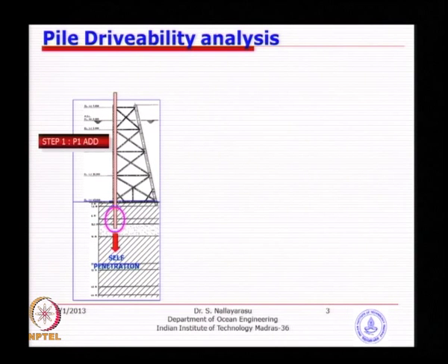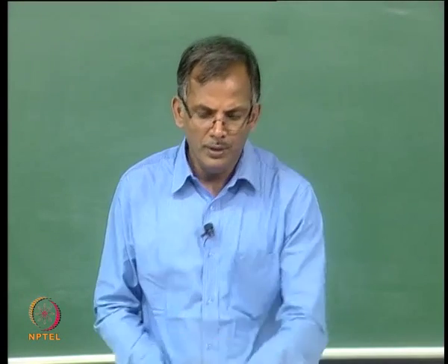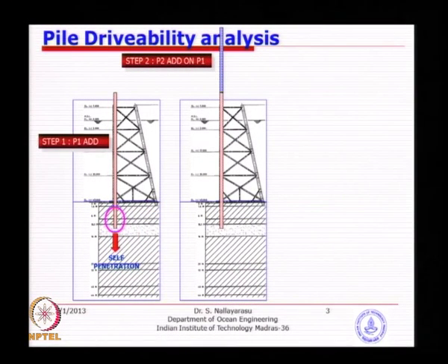So, the length of the pile needs to be adjusted in such a way that it does not stop at a layer that you do not want. Predominantly we do not want to stop at a sand layer, because restart driving will become really troublesome. So, basically the pile driving is a sequence of activities. It can take any direction depending on what you have decided.